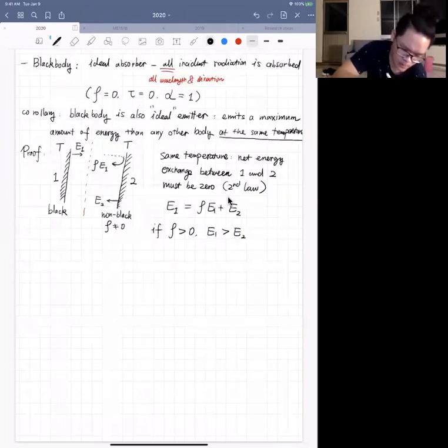So basically, a black surface is an ideal absorber, but at the same time it's an ideal emitter. That's another challenge for solar design. As I mentioned, if you want to design an absorber to absorb as much solar energy as possible, you have to pay a price. There's no free lunch. Again, this is determined by the second law of thermodynamics. If you have a really good absorber, typically it also emits a lot of energy, so then you lose a lot of energy in the process.